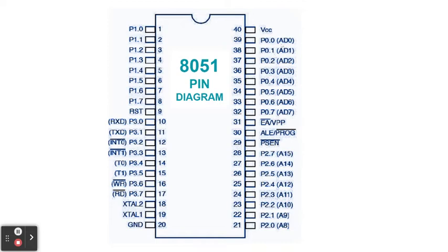It can be used for address and it can also be used for data. That's why we can use this for D0 up to D7 and also A0 up to A7, aside from input or output. And lastly, we have the VCC, which is the power supply of positive 5 volts.